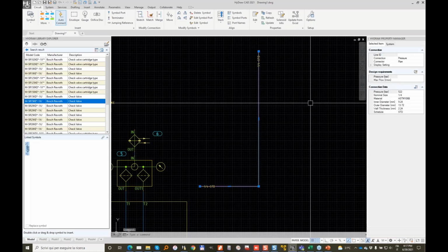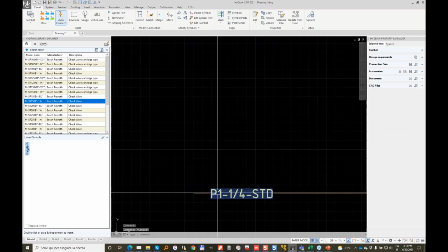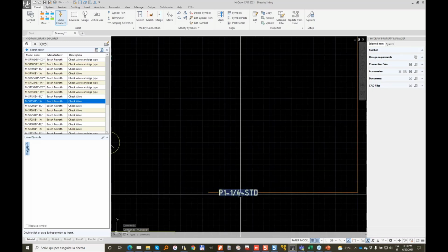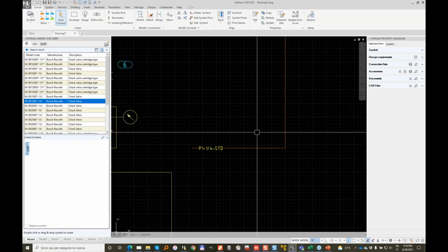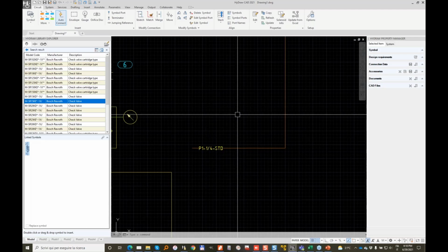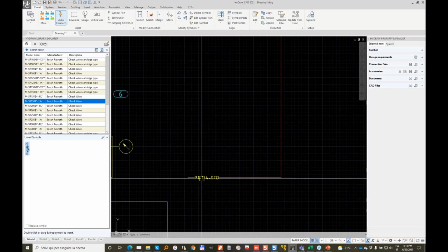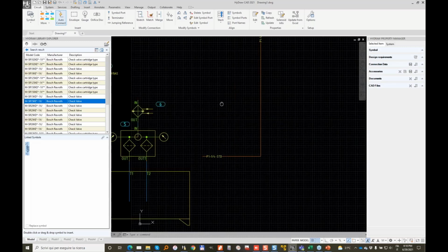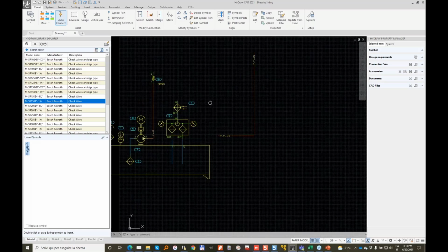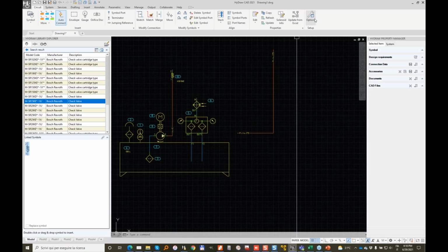In addition, we can type in the line ID. So let's say that my line is called P1. And as you see now, the ID is combined with my display format for the connection line in one row. We decided this way because normally connection lines in a complex diagram are going parallel with not much distance. So we try to put the text along the connection line, overlapping, so that it helps readability. Now we can make a pipe list, and we have the possibility to configure our pipe list.